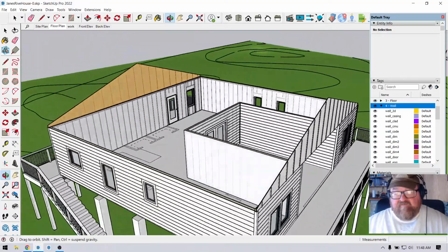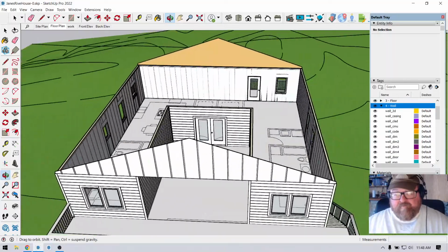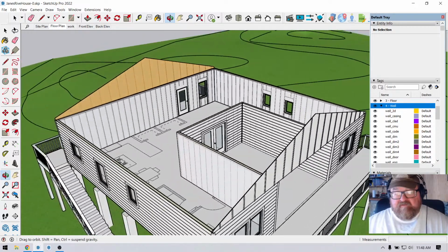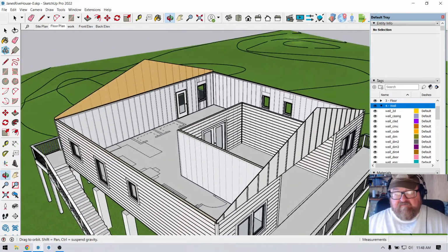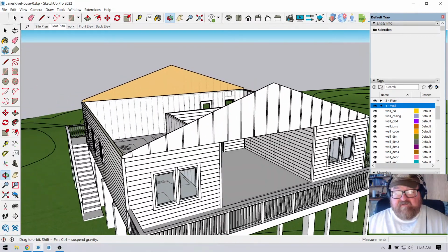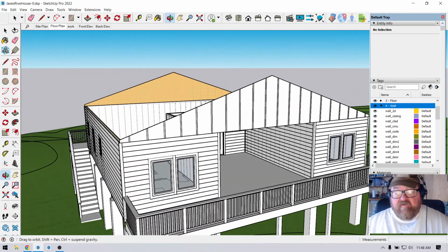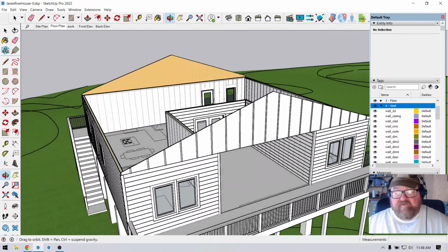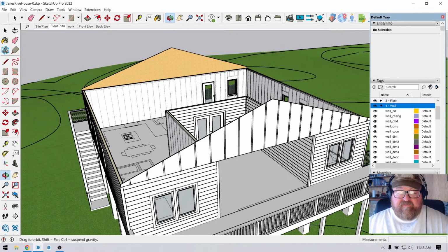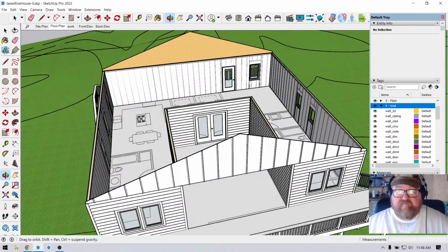Well, you couldn't. You could use rafters if this wall went all the way through. Because what you could do is build a little short wall right here. And so the span of the rafter would only be from here to here, then from here to the center, then from the center to there, and from there to the center. You'd break up the spans.